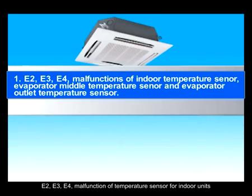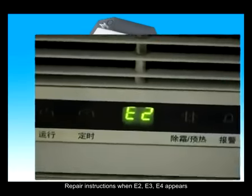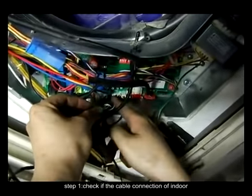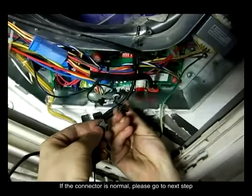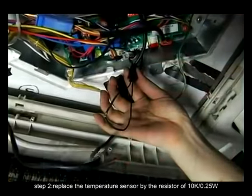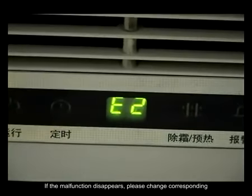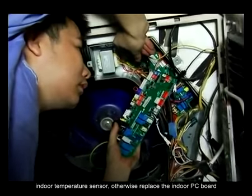E2, E3, E4, malfunction of temperature sensor for indoor units. Repair instructions when E2, E3, E4 appears. Step 1. Check if the cable connection of the indoor temperature sensor is correct and reliable. If the connector is normal, please go to the next step. Step 2. Replace the temperature sensor with a 10K per 0.25 watts one. Then check if the malfunction disappears or not. If the malfunction disappears, please change the corresponding indoor temperature sensor. Otherwise, replace the indoor PC board.